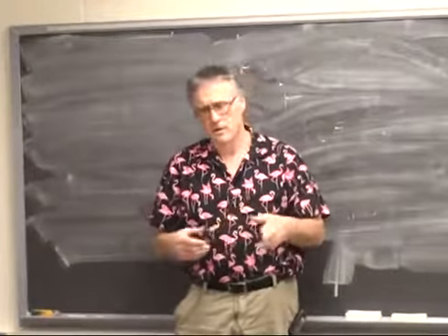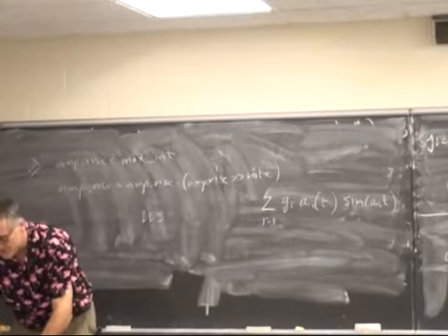So this is sine omega_i t. The DDS for each omega_i t is going to give you the sine, and then A_i is going to be calculated by finite difference equations. We've got C code that does this. I'll give you some examples here.